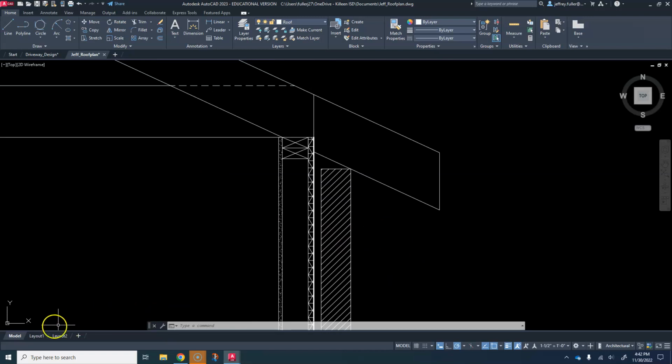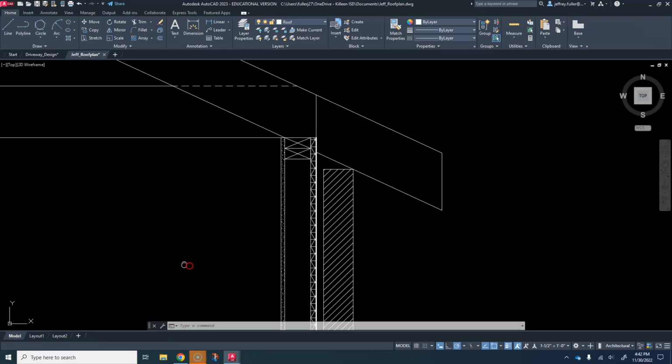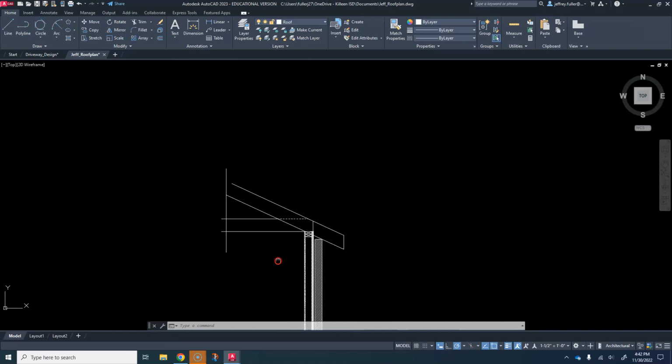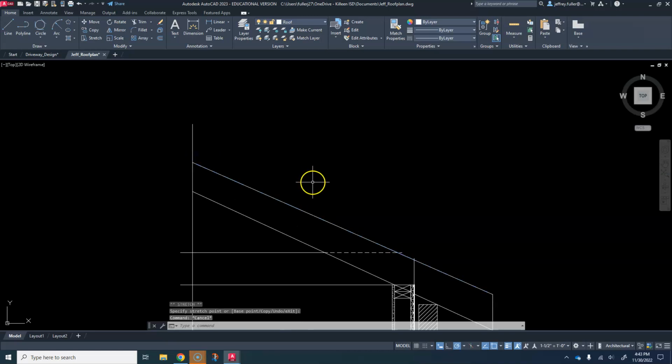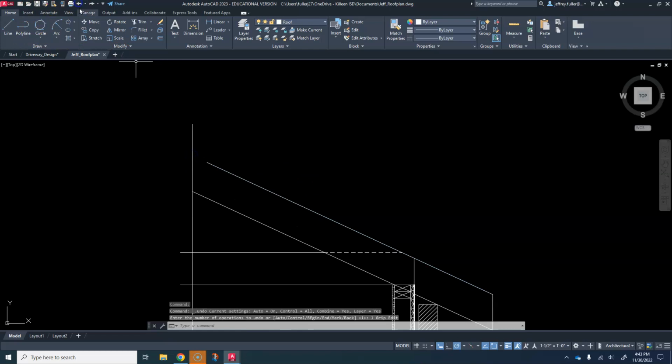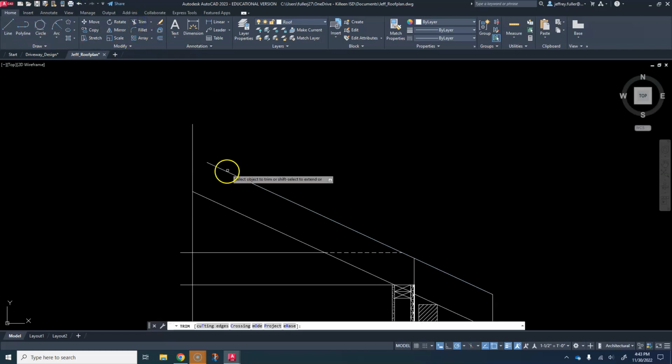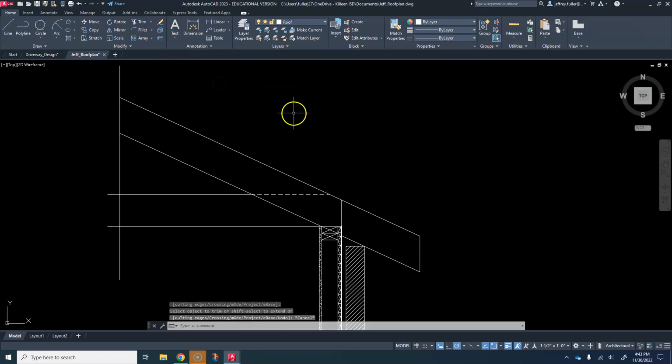All right, so that has gotten us this far. Let me see how far we are into the recording. Okay, we might be far enough. If we've gotten this so far, this is basically our roof. Go ahead and pull this on up to here. And I messed it up. Hit the back button if you did what I did. Do it like it should do. Hit the trim tool, hold the shift button down, and extend it.